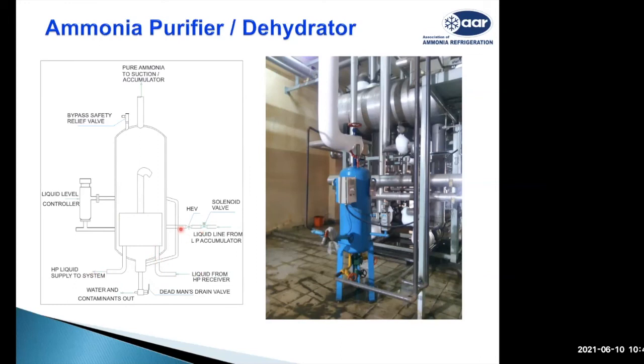So what happens here is that the ammonia sample, which is taken from a pump vessel or evaporator drain points, comes into contact with this hot refrigerant. The hot refrigerant will evaporate any ammonia content, and that will go back to the system.